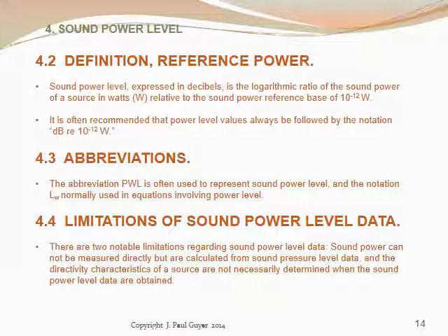There are two notable limitations regarding sound power level data. First, sound power cannot be measured directly, but is calculated from sound pressure level data, and the directivity characteristics of a source are not necessarily determined when the sound power level data are obtained.